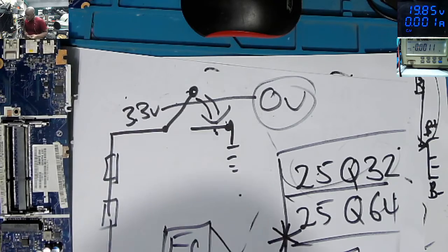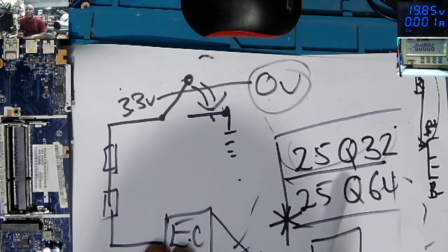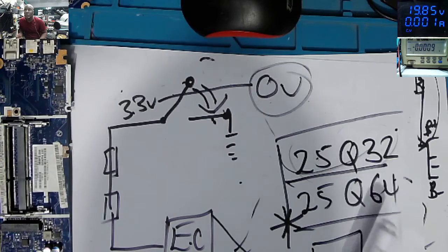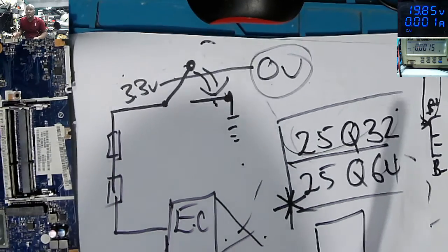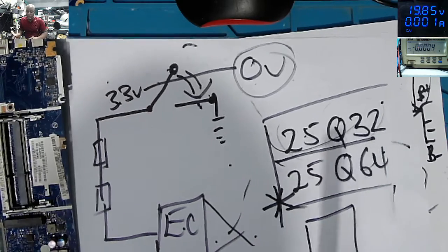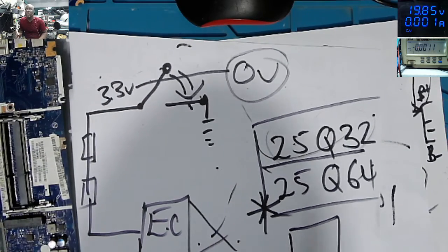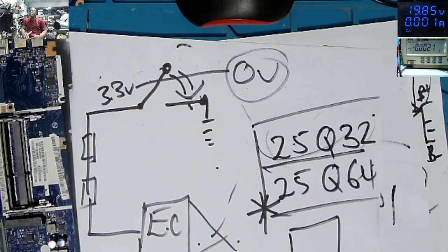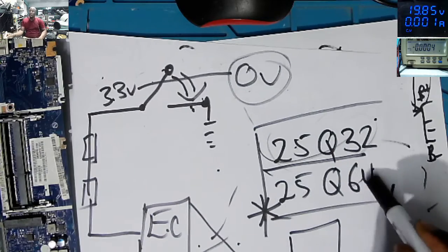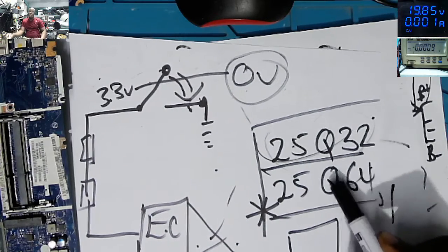Yeah, this is some kind of confusion on the new models of laptops and motherboards. It's bringing confusion on repairs. You see the laptop maybe is coming on and goes off. You think of reflashing the BIOS chip. You don't know which BIOS chip to choose. Start with this one, the main one.